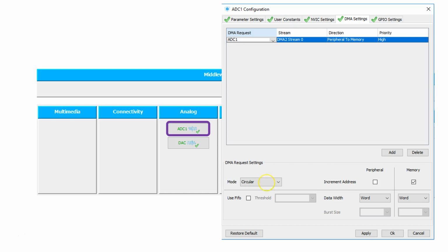One thing to keep in mind, if you look at the STM32 F7 manual on DMAs, you'll find there are a number of streams of the DMA. It's not just the ADC, which is on the APB bus, that could request a DMA. We might have a UART doing a DMA to move data from a serial port to memory, or from memory to a serial port, and all that kind of stuff. So there are different streams you could select. ADC1 happens to be on stream 0. Those are just a few things to play with, and that's basically all the DMA settings we need to do. Let's say okay, and move on.